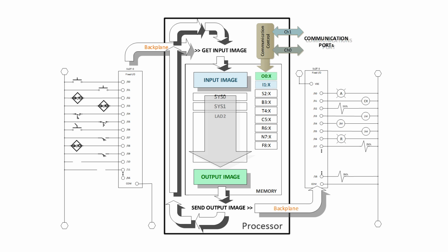Some of the more advanced systems that they call PACs, Programmable Automation Controllers, are a little bit more complex. They're a little bit more efficient in the way they handle things, but still, you write a program that reads from the data table and writes to the data table, and those results then are felt in the output image to control your machine.